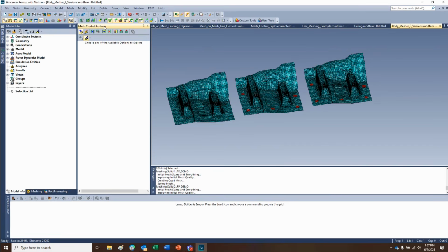It makes life so much easier if you don't need to non-manifold everything together. And the other thing with the Mesh Control Explorer with the propagation stuff is that other thing I showed you with the edge replace. You can actually just use that edge replace to get everything lined up and not even have the non-manifold added at the end as well.